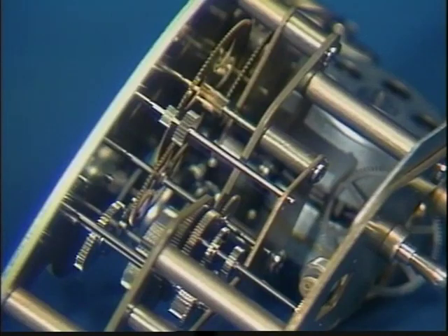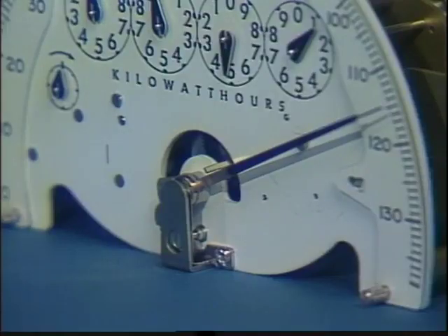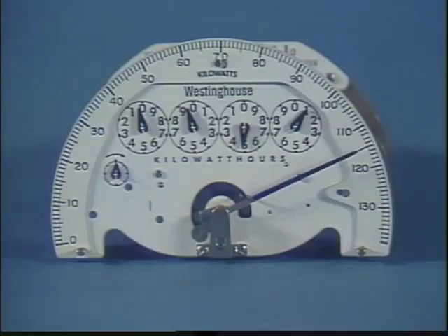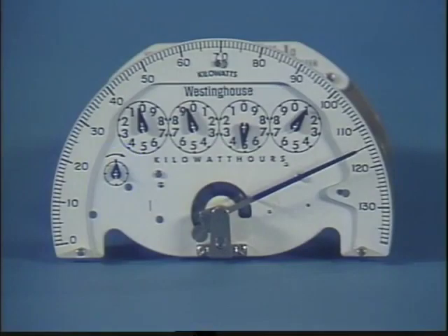When the disk shaft rotates, it drives a gear train. Part of the gear train turns the dials that indicate kilowatt-hour use. A separate part of the gear train causes the pusher arm of the demand register to push the demand pointer upscale. While this is taking place, a timing motor is turning a timing gear train. Demand meters typically have a time interval indicator, like this one, to indicate about how much time has elapsed at any point during an interval.